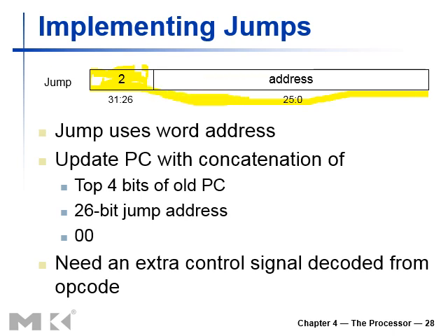So what we have to do is, if we encounter the jump instruction, definitely that will change the sequential flow of execution. We are not going to check any condition for that. So we have to assign the program counter the jump address. Now what would be the jump address? Would it be these 26 bits, or do we have to manipulate these 26 bits in order to generate a jump address? Because the program counter is a 32-bit register and these are 26 bits.